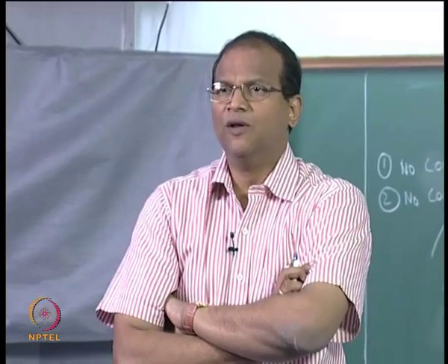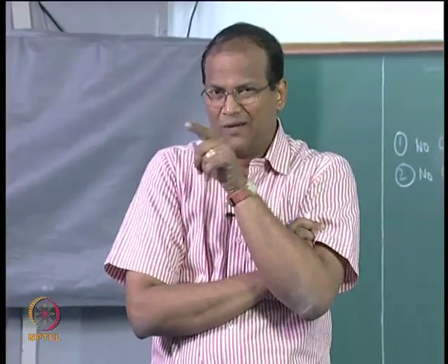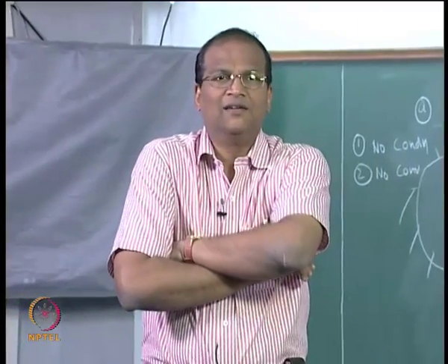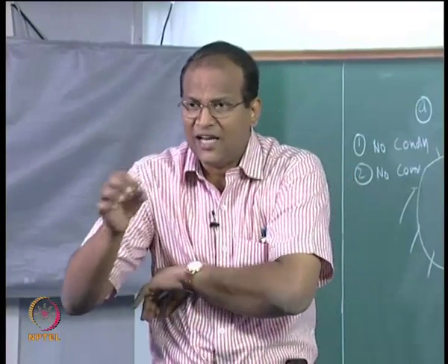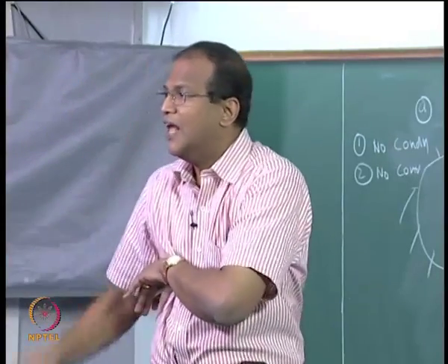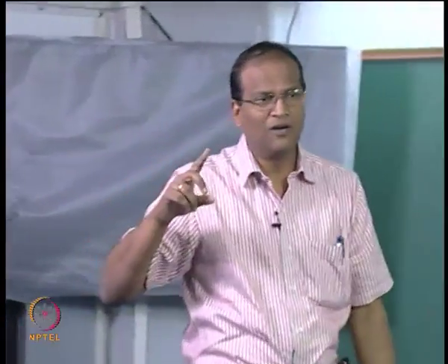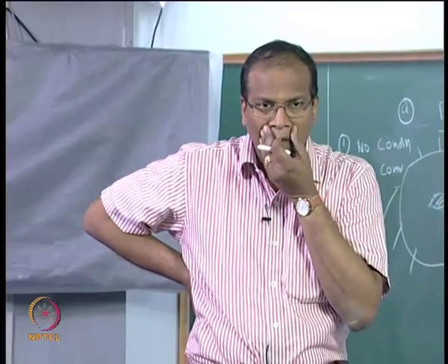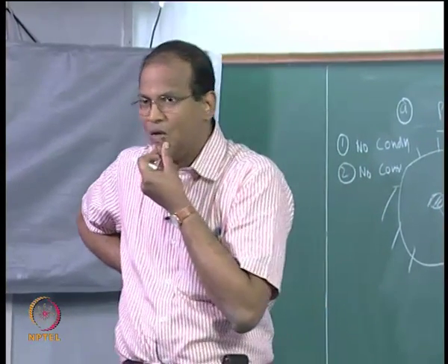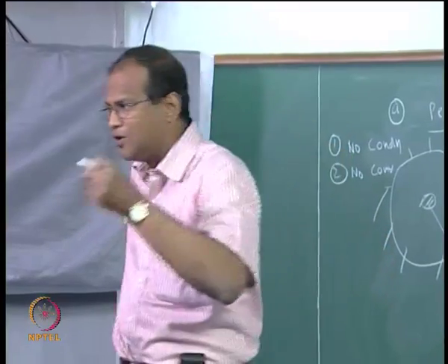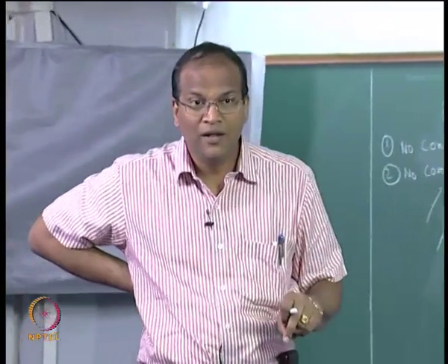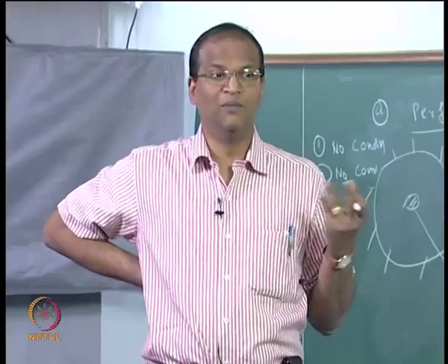Now, thermal equilibrium is established in an evacuated enclosure in which a black body is present, but the small object is a black body. So what is the story there? It is absorbing exactly the same amount as it is emitting, because if the emission is not equal to the absorption, then there is a net rate of change of enthalpy inside the black body, as a consequence of which its temperature has to go down or go up, which is again forbidden because equilibrium has already been established. Therefore, the amount of radiation emitted by the black body is exactly equal to the amount of radiation absorbed by it. Since it is a black body, it is absorbing the maximum amount of radiation, therefore it is also emitting the maximum amount of radiation.